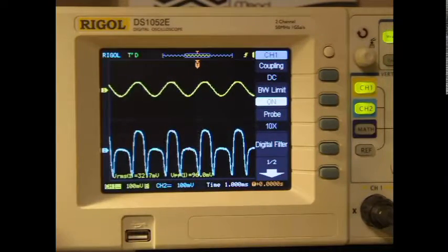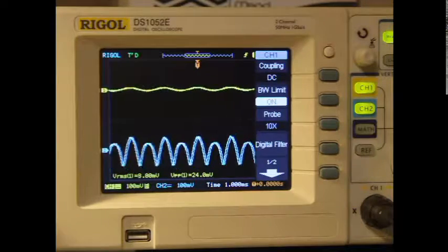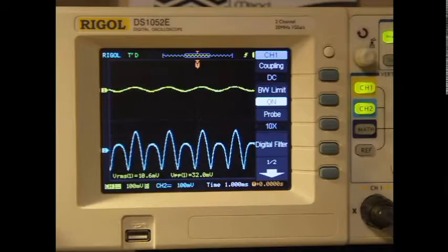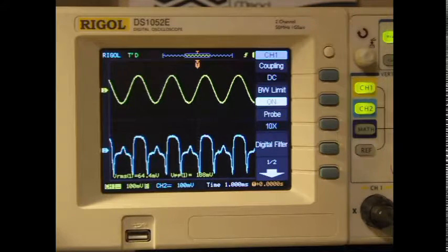And of course there are other strange things going on in here, because there's extra gain, and so it's kind of distorting the signal a little bit before it even gets rectified in that way, because we're overdriving some of the internal circuitry. You can sort of see more of that or less of that as you turn the input signal up and down. You can see it does really strange things. You get to right around here, you get a little nipple there on those guys, and that's pretty weird. You can see that the humps are different heights.